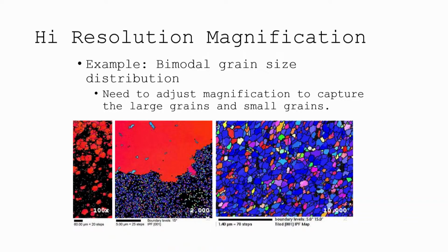This is a nice experiment I was doing one time on copper films. If these copper films get to be about a micron thick and you anneal them, they go from almost all 111 texture to a large grain 100 texture, 111 fiber to 100 fiber. If you don't know what that means, then 2 weeks from now you will. We'll talk about it.